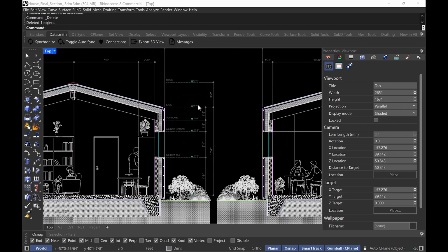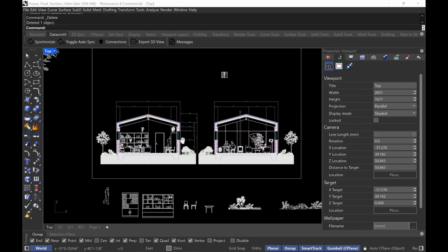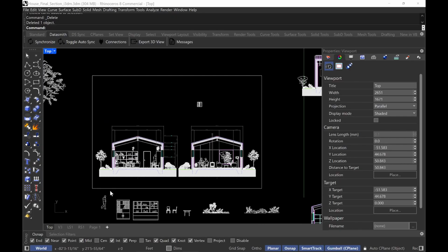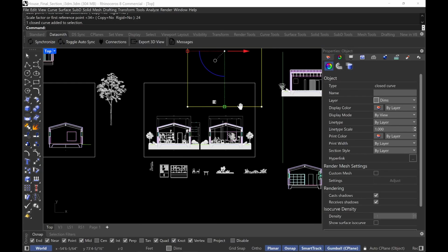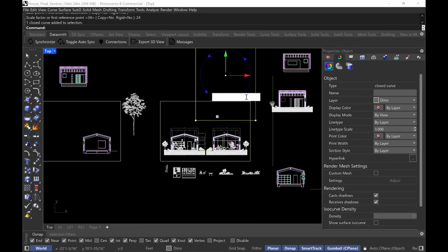The other thing is just the sheet size again. So we're going to use this reference rectangle that you see here as the scaling sheet size. And that's how we're going to scale our drawing in Illustrator. It's a very easy reference to use. And so just in case you forgot, I'll do a rectangle from the center, right? And I'll do 2 feet by 3 feet, right? And you just scale it by a factor of 24 because that's the scale factor of a 1/2-inch scale. And you just rotate it, and that's just going to be a reference sheet size, okay?